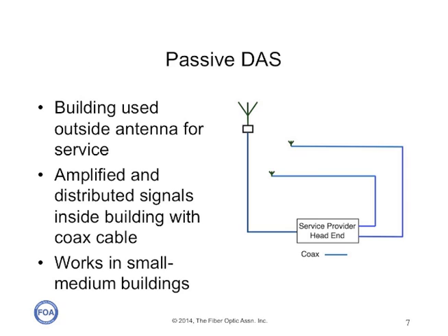There are two different types of DAS, passive and active. Passive DAS systems are simply repeaters for signals to and from an outside antenna. The electronics amplify the signals and connect to remote antennas over large, typically 12 to 25 millimeter coaxial cables. Besides the obvious noise problems with all analog systems, the coax cable runs are limited to about 100 meters, 330 feet, making this a difficult system to use in large buildings or structures.